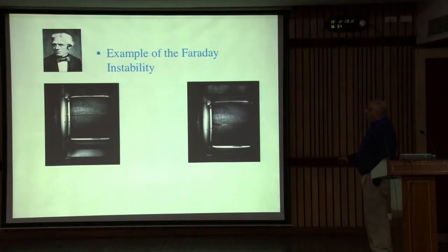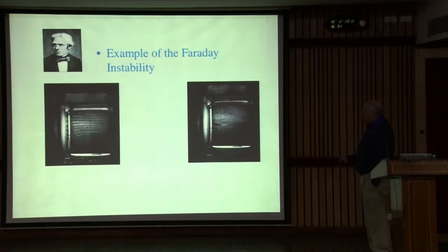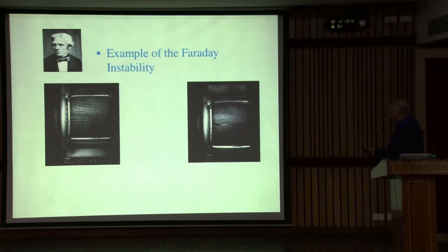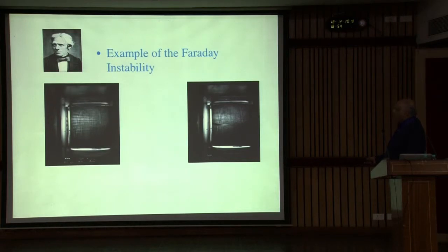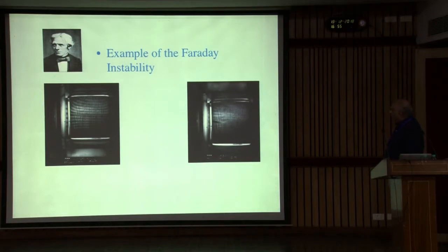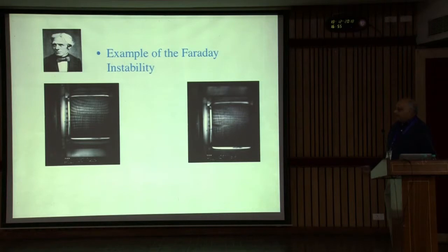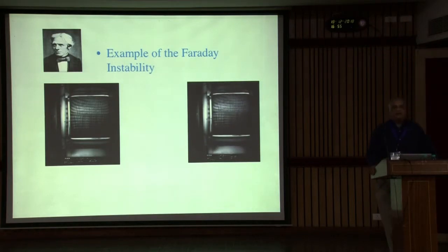There's two liquids, and you can barely see an interface. The whole container is going to be moving up and down. And as it moves up and down, you might see a slight deflection of the interface, but nothing really dramatic. The right container is going to move at precisely the same frequency as the left. In fact, it is the same container, but moving at an amplitude of motion of about 0.5 millimeter more. And you're going to now see the interface deflect fairly substantially. So what has happened is in the right container, we have attained a state of resonance.